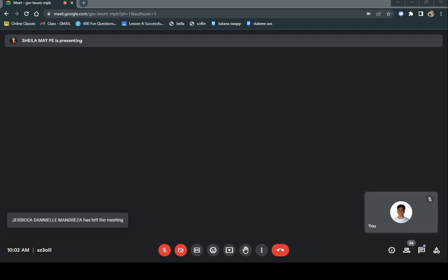So that's just VDD minus VD over RD. VDD is 18, VD is 12, RD is 2000. So 18 minus 12, that's 6 divided by 2000, so that's 3 milliampere.